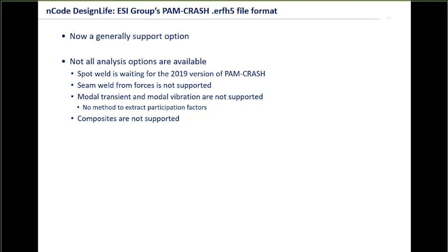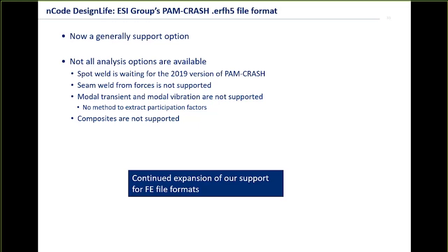Seam Weld is not currently supported because forces are not supported, so we can't get the forces out at the moment. Modal transient and modal vibration are not supported because there's no way of extracting the participation factors at the moment. We're looking at doing that in the future. And currently composite elements are not supported. Again, that's a continued expansion of our support for different file formats, and that's an ongoing activity to keep our support up to date and to add new file formats where appropriate.